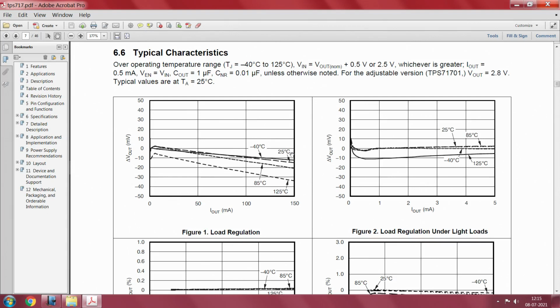Supposing you place the LDO as part of an airplane, okay, and it is exposed to outside ambient, your embedded node is collecting data from an airplane at minus 40 cruising altitude so you get minus 50 in that range, then there is hardly any drop in the output voltage even under high excursion of current being drawn in some sort of very short duration.